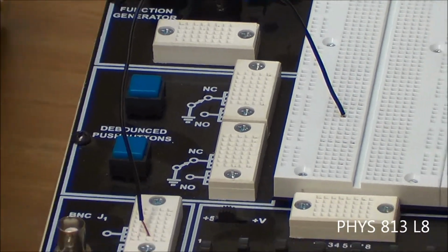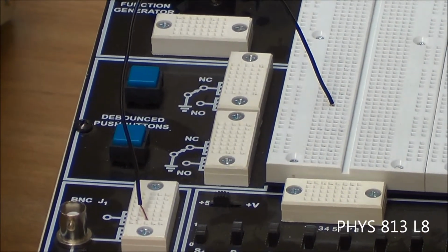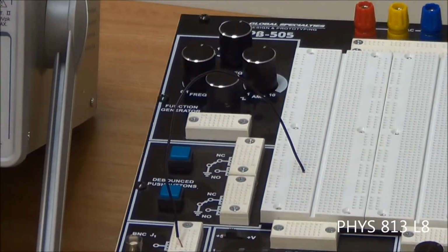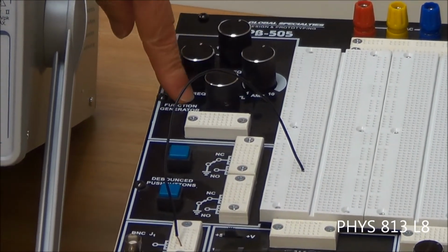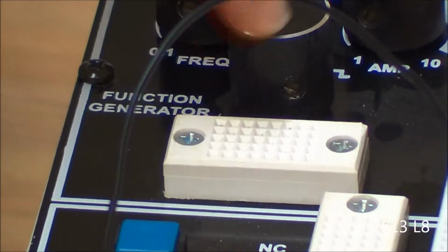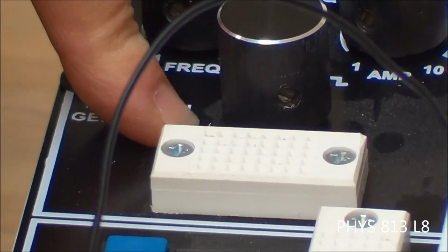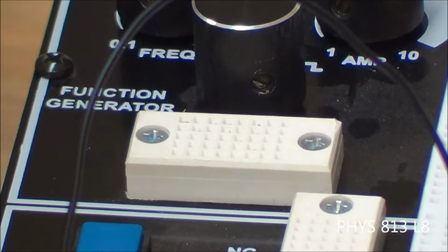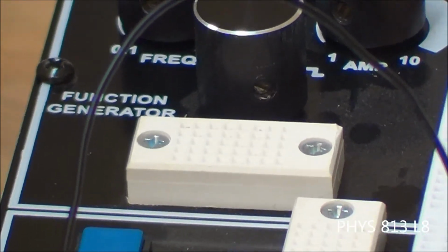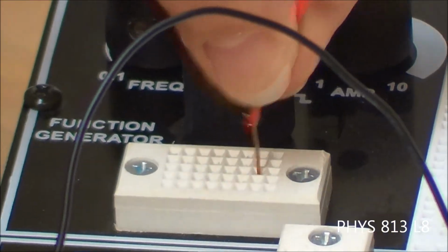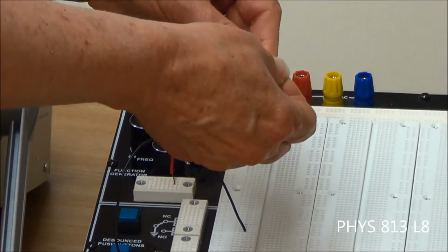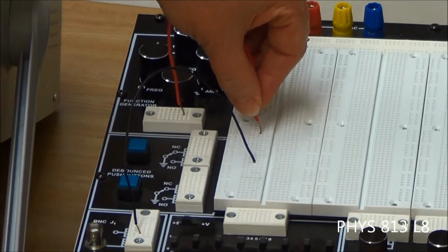And then we need to get our signal from the function generator up here. And if you notice right below the words function generator knob, there are several columns here. There are 2 of them that say TTL. That's actually transistor to transistor logic, which we're not using now. So we're going to just put this into someplace over here on the right hand part of this, and then it just says to put it into the circuit board a few rows from this previous black one. So I'm just going to put it there.